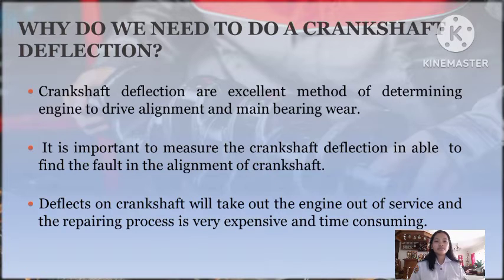crankshaft deflection, because in our engine, a bending of our crankshaft might lead our engine or our system into destruction. Then it is important to measure the crankshaft deflection and be able to find the fault in alignment of the crankshaft. So as I've said, if there is any misalignment, through doing crankshaft deflection we are able to find the fault or the cause of the misalignment.